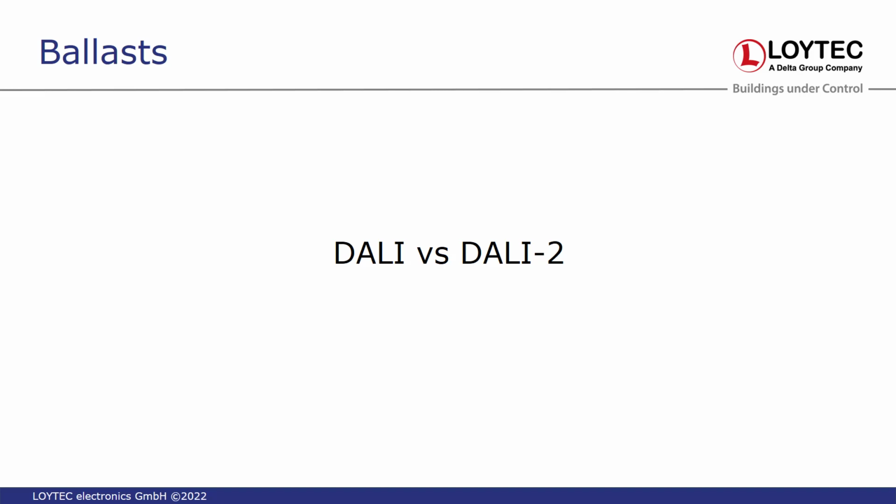Yes, I think the point here is what DALI 2 is doing and what Hans showed at the beginning of the presentation. In DALI 2, you have the possibility to have a standardized test. For DALI 2, there is a test fixture and there is a number of tests that you need to execute with your ballasts. This is some timing issues. It tells you how fast you react after power on and all kinds of timing parameters. And you need to fulfill this.